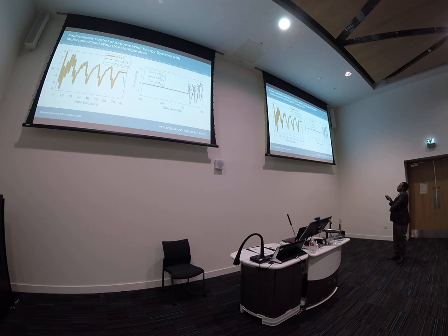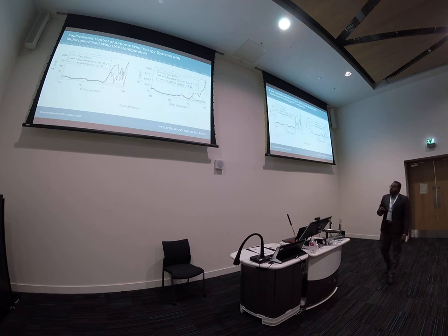Here you see the moment produced by the VTOL system. After maybe 3 seconds, the fault detection and isolation algorithm will disengage the control surfaces, and we'll use the VTOL system instead. And you can see that we start to produce some moment by the VTOL system. This is the residual which we use to detect the failure.